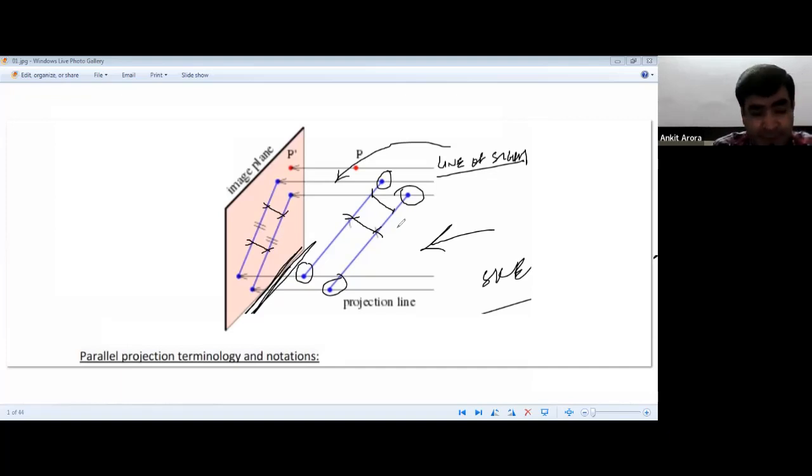When we talk about perspective projection, an object is considered more realistic. Obviously, that is how it will look to the human eye. But parallel projection has its own benefits. When you are at a site, you are not going to be there to elaborate each and every line to the people who are going to be constructing it. So you have to have a drawing, and it has to be exactly the way it is, rather than how it will be seen, because that may create confusion as well. Perspective is more related to the human eye and photography.